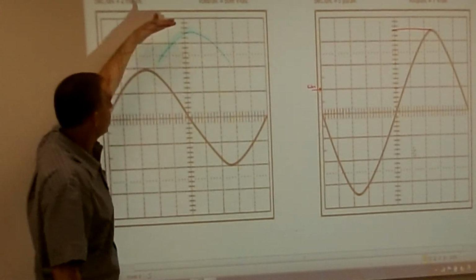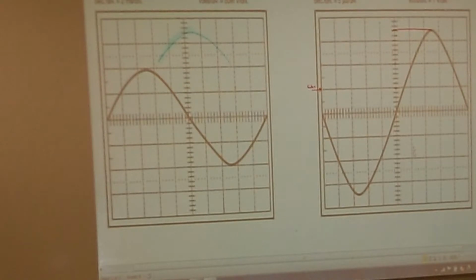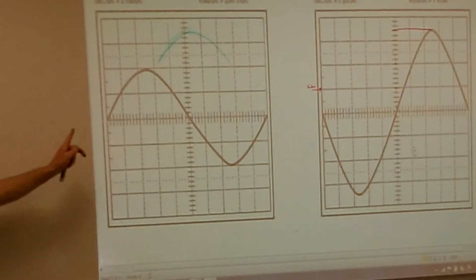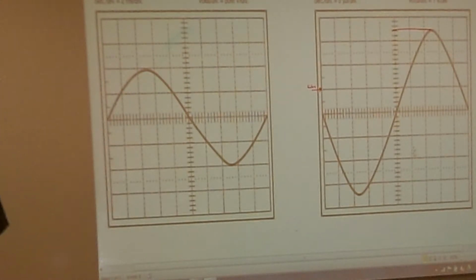Realistically, we really can only get down because each subdivision is only equal to 0.2, right? So the smallest number that we can really measure is, let's say for example, 2.4. But if we're halfway in between, then we could go 2.45. So you're really only going to be 2 decimal places. That is the most accurate you're ever going to measure on an oscilloscope. But again, not so critical; what matters is whether the waveform is there. I always make sure it's right on the line so you can definitely see it, or if you're close and calculated everything else out, I'm not too worried about that.